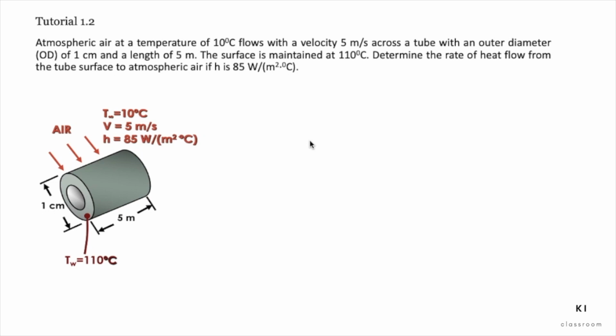Before this we had conduction. Basically, in order for us to determine whether our problem is conduction or convection, one way is the value given. This is the easiest way. If the value given is k, that is thermal conductivity, it means our problem is conduction.